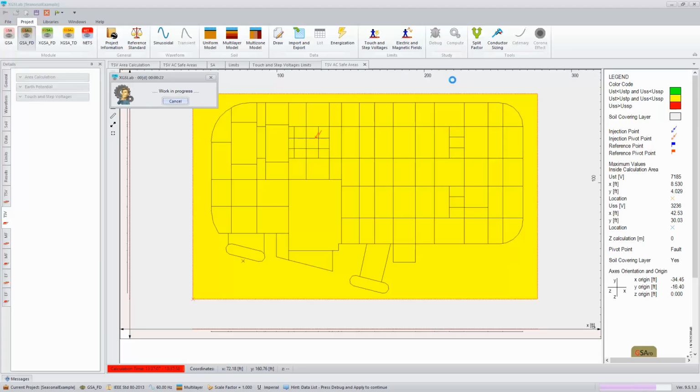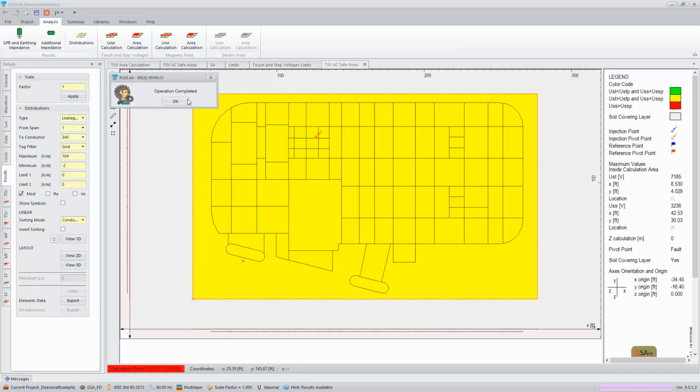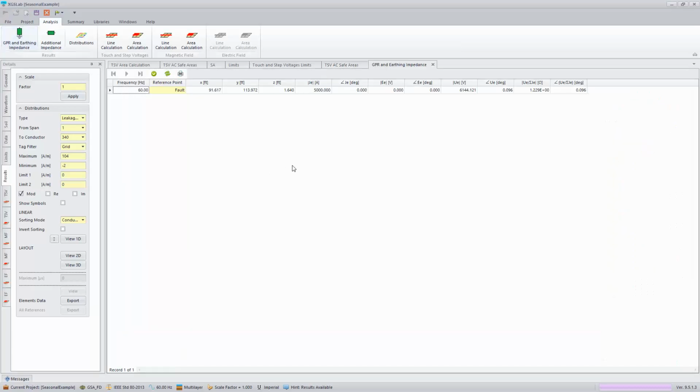And once this completes, I remembered I have to change the touch and step voltage as well. So first, we have a little bit of a reduction in our ground potential rise. We were at 1.8 ohms for our January 1st soil model. Now, with those additional ground rods, we're able to reduce that resistance to 1.2 ohms, and that reduces our corresponding ground potential rise.